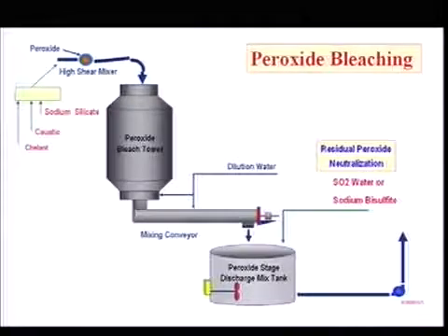So you have to ensure some peroxide is present there, so it is not darkening your fiber. Typical value is 5 to 10% residual peroxide that can be present in this tank. That means you have a good bleaching going on when you have some residual peroxide there. You didn't do the alkali darkening.